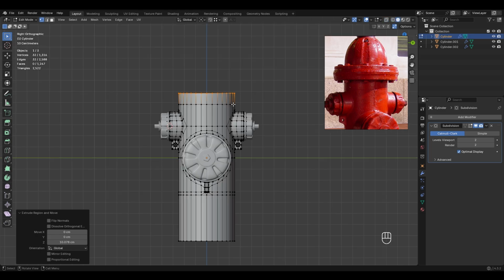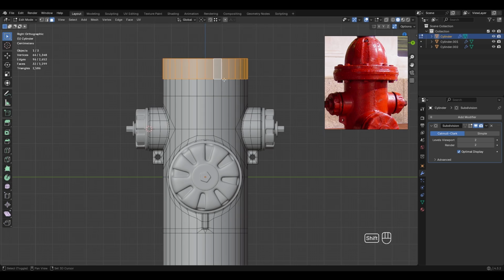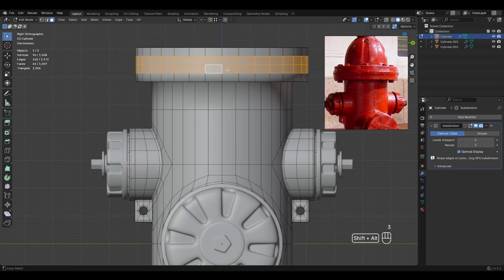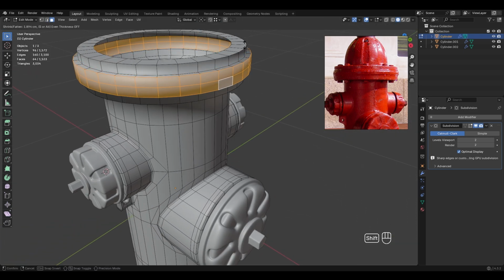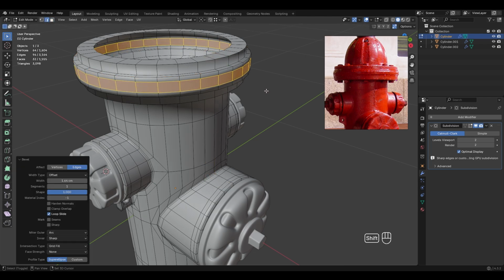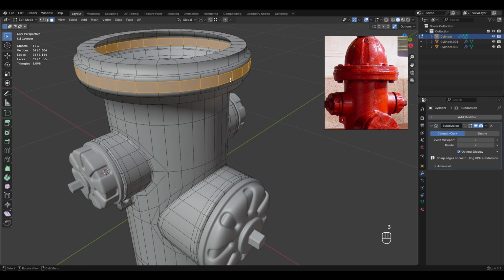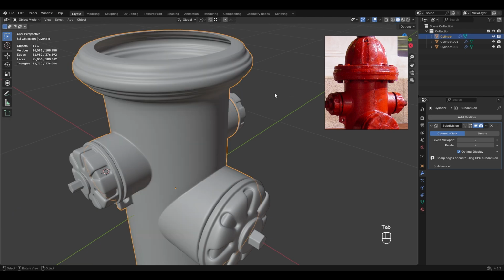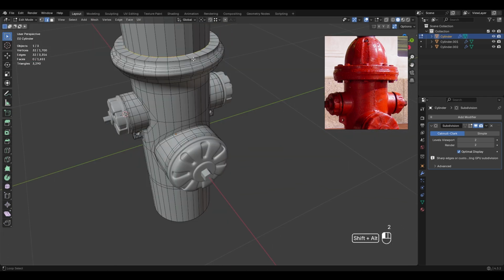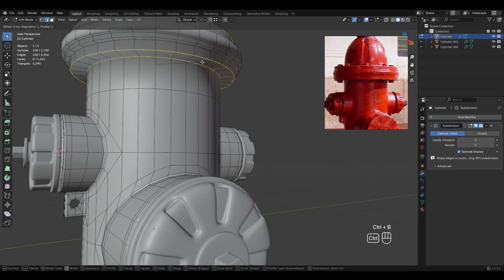And I'm going to do another extrusion like so, and then select these faces and right click, extrude faces along normal, and then do some edge loops and select these and another extrusion along normal, and then again select these edges and do a bevel like this, and do another extrusion from your faces. I'm gonna select these edges and do an extrusion like so, and then I'm going to select these and do a bevel for 2 segments and around here.